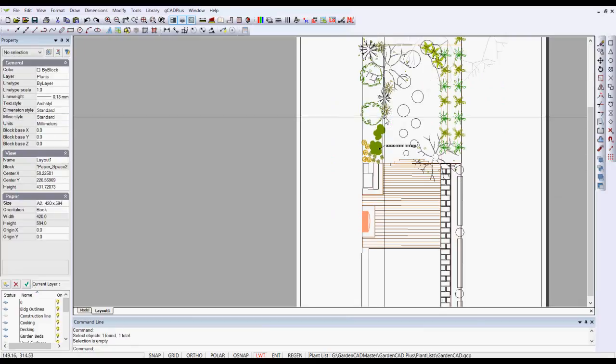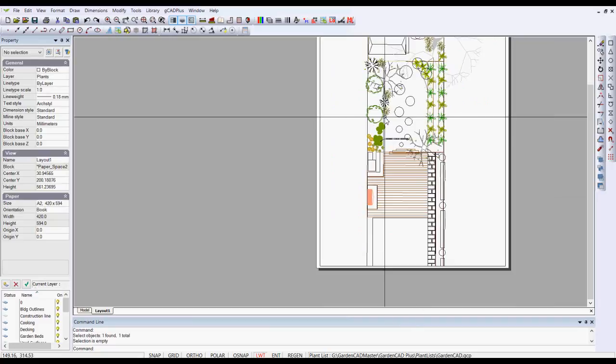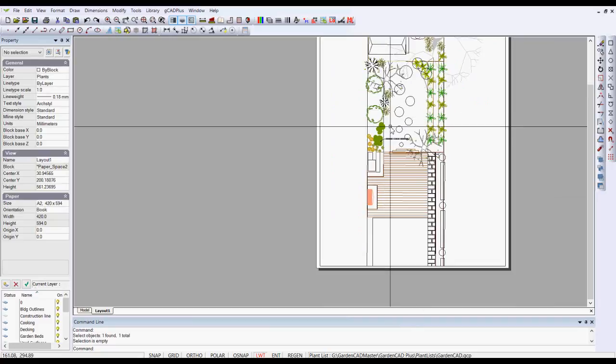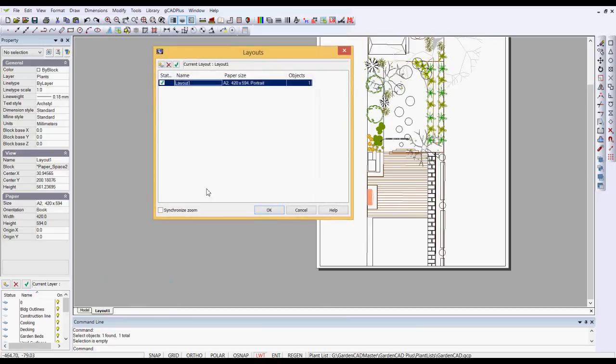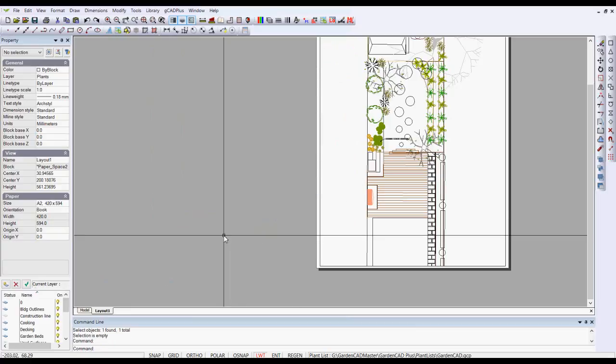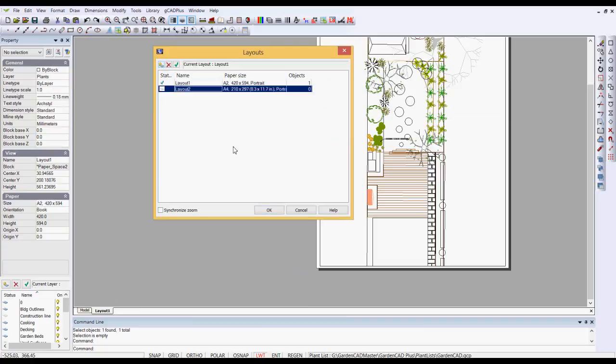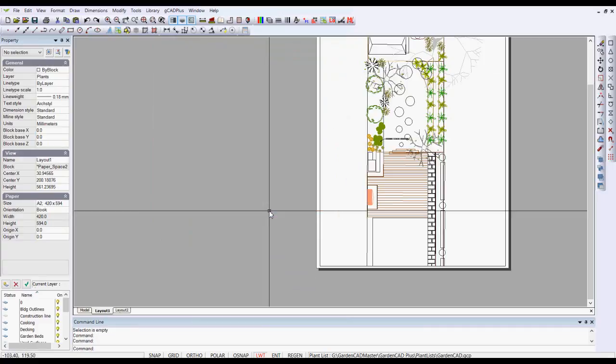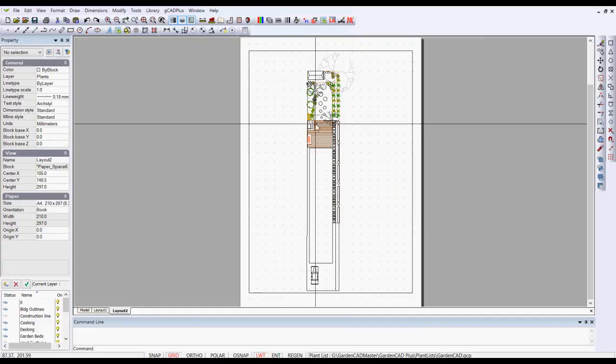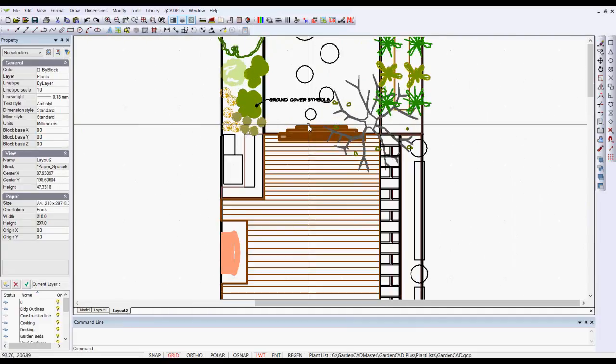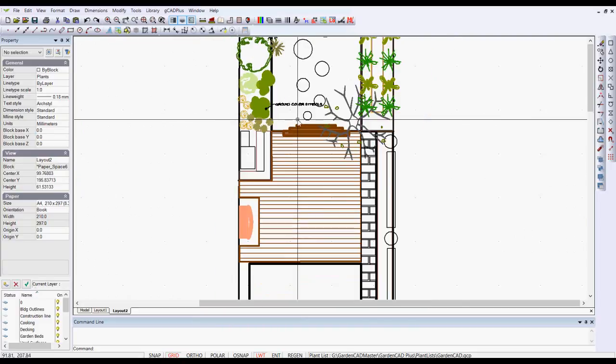The other approach to handling line weights is in some ways a better approach, because if you move to a different size sheet, this layout sheet here, we go to the Layouts Manager, is an A2 sheet. Now if we did another layout, made a new one, let's do that, Format, Layout, and we'll make a new one on A4, and we'll make it Portrait, that's fine. And if we look in here, because it's a much smaller piece of paper, your line weights are massive and get distorted.